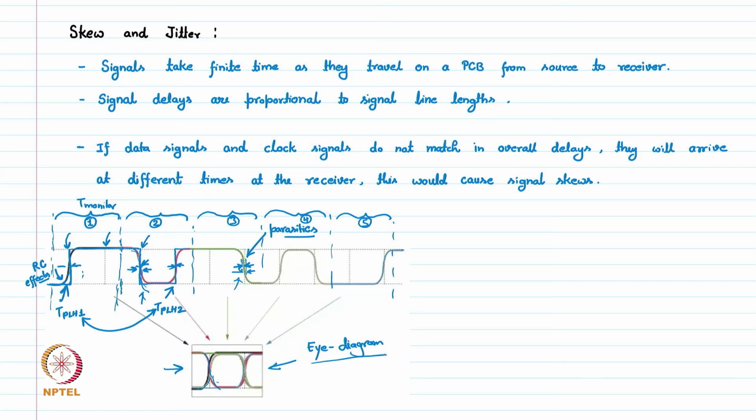So in this eye diagram, we can monitor multiple things. For example, if this rounding is very high for multiple cycles, we need to remember that we are simulating or measuring these delays for a large number of cycles. For example, 1000 cycles we are superimposing. So for all the 1000 values, we'll have different waveforms that will tell us what the worst case and the best case delays are here. So this is the delay.